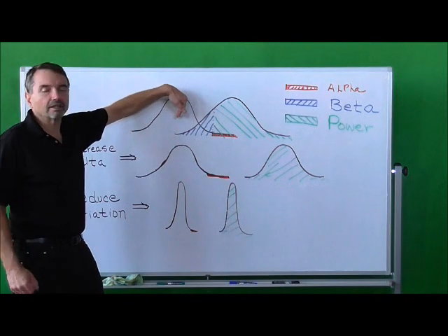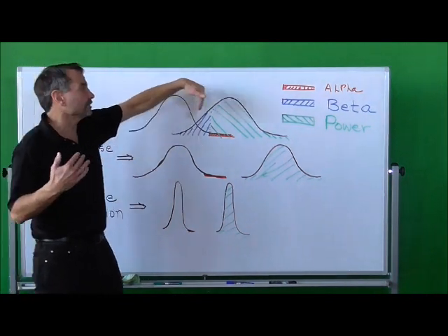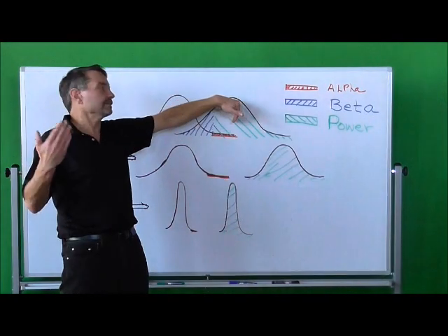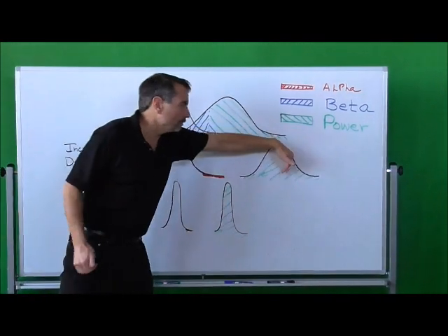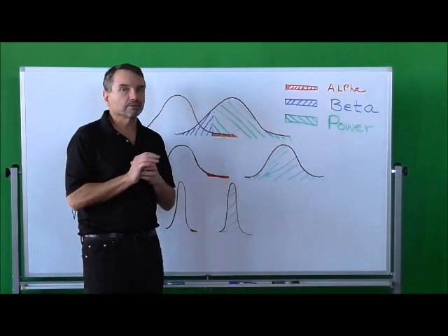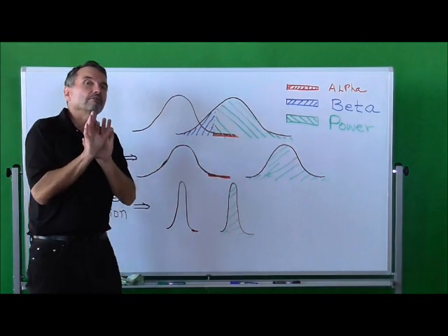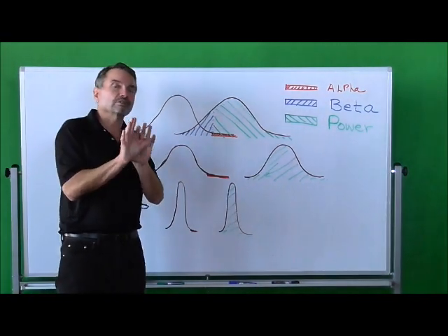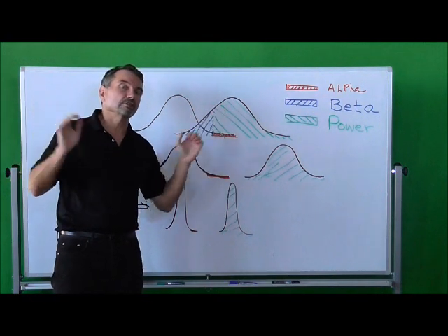If this was an experiment that started off with an outcome of 45 on the yield, and this one was up at 65 on the yield, then instead of moving it for 45, move it up to 85. Now sometimes you can do that, sometimes you can't. But the base level concepts of DOE, for at least the initial effect, says move them out as far as possible without destroying the equipment.